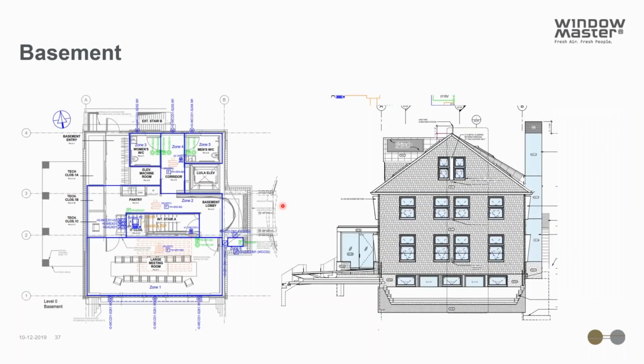One of the design issues with House Zero was also the conference room here in the basement. As you can see, the ventilation can only be based on single-sided ventilation, which is a bit of a problem due to the large density in the meeting room. A very special solution for this building was to create a solar chimney.